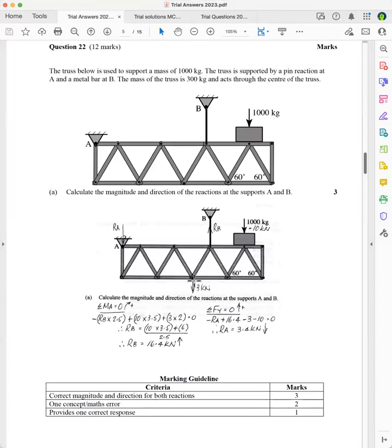for that. And look at all the forces, they're all vertical. Even though you've got a pin here, there's only a vertical force there, because these other forces are all vertical. There's no horizontal component to those forces. And so these questions are relatively easy when you put all of the forces on. And I would even show the examiner that you know that that's 90 degrees by putting a little 90-degree bracket there, and a little bracket there. You'll definitely get 1 mark.